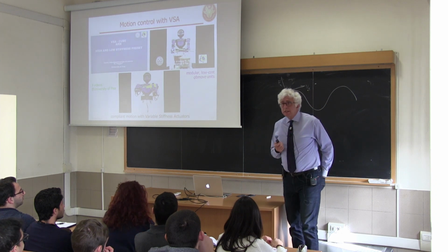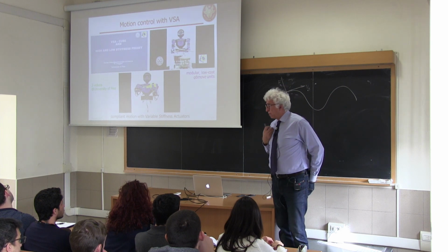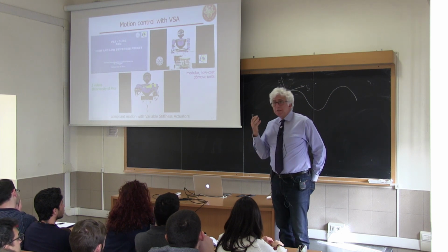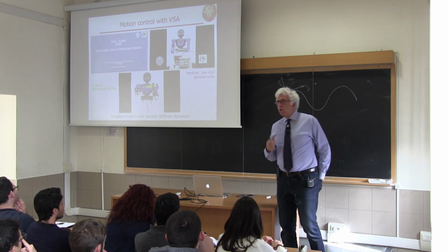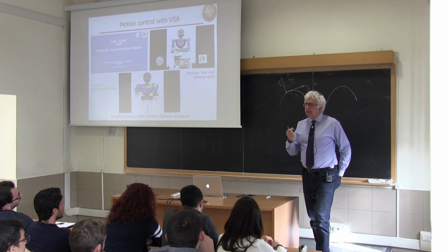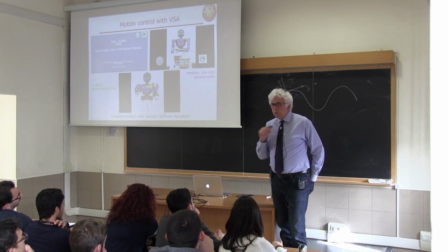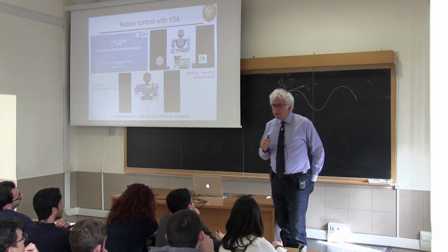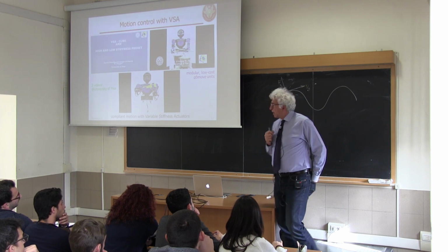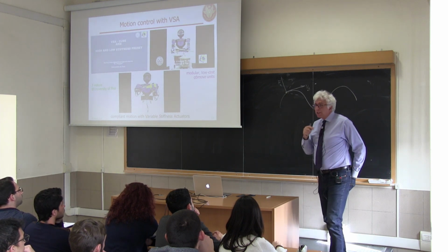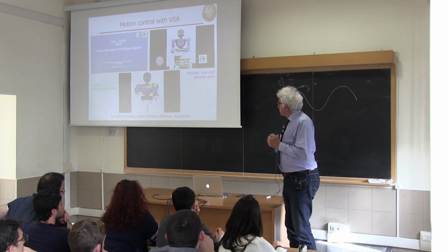So this is another use of variable stiffness actuation, changing the stiffness on the fly. The last use is, in fact, a matter of safety for the robot itself. A very stiff robot performing a non-typical action like making a hole with a hammer, where there are impulsive forces acting on the rigid structure, will not sustain impulsive forces of this type if there is no compliance inside the structure. Okay? So not only safety for the human, but also robustness for the mechanical part.